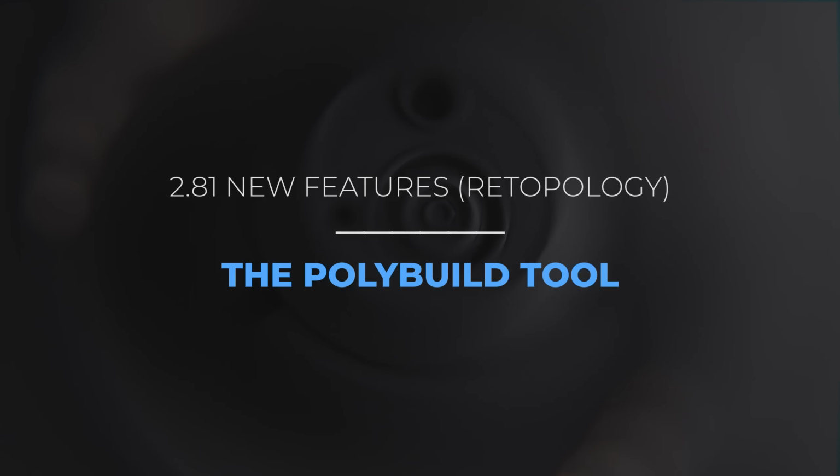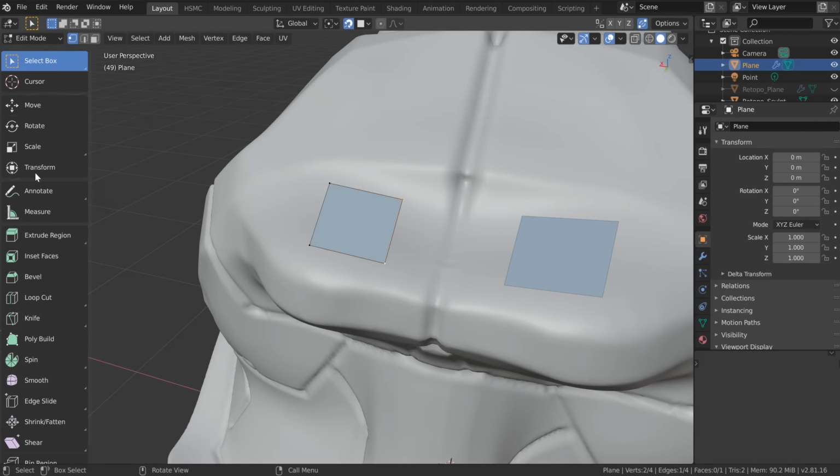Now is the time to get on with the modeling. Normally, I would like to keep things on the select box, and most of these I would just use shortcut keys for, but there is the Polybuild tool that we should take a look at where that is right now. So we're going to switch to that, and you'll see immediately we get some overlays here, the blue edge that you can see there. And now that means that we're not going to be able to do a box selection, unless we press B, of course, and do it that way.